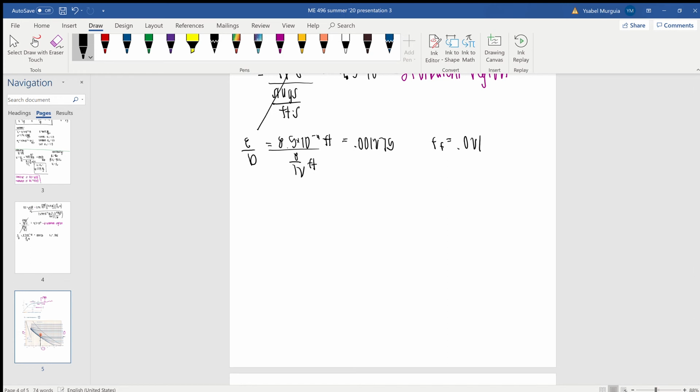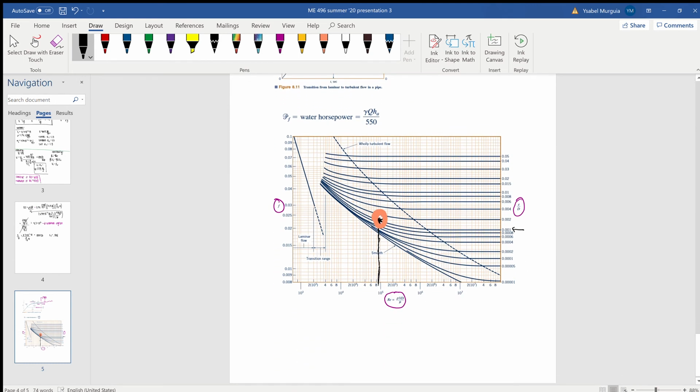And you can calculate this using the Moody diagram or by plugging it into an equation, the Colebrook equation. This friction factor is a function of Reynolds number and the roughness over the diameter for turbulent flow only. Again, emphasizing that laminar flow is not dependent on the roughness or the density of the fluid, only the viscosity. So in turn, it is dependent on the diameter but not on roughness, because the flow is smooth compared to the turbulent flow, which is just all over the place.